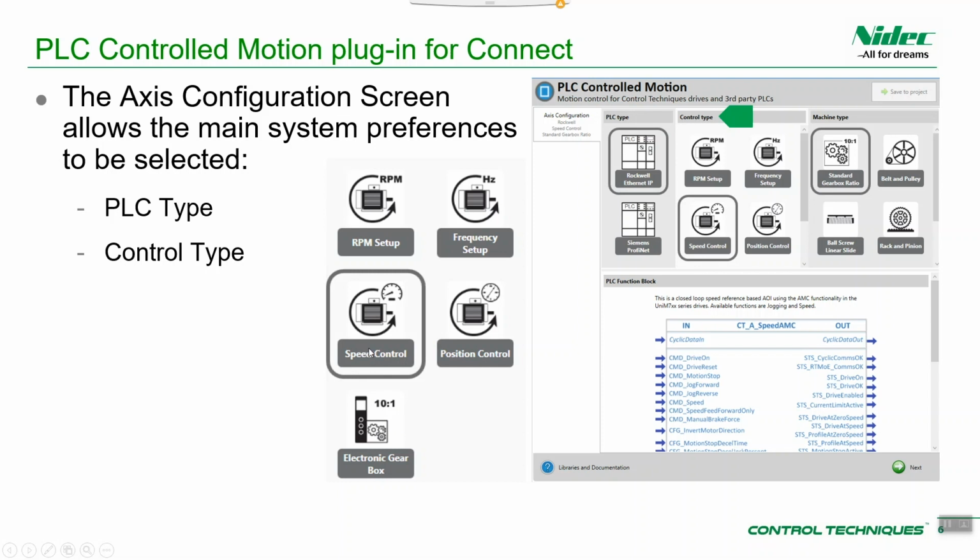One that's a simplified speed control interface, but in real engineering units, whatever user unit that you'd like to choose. That could be millimeters per second, something like that, or millimeters per millisecond. A position control interface that gives you indexing type capability, and lastly an electronic gearbox interface. That gives you the ability to follow a real-time motion reference over synchronous communications.